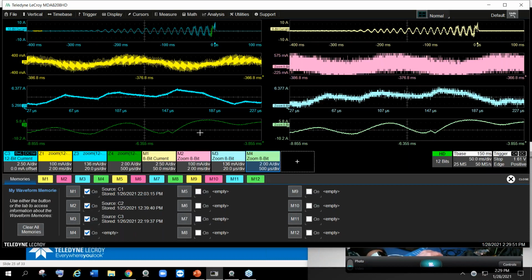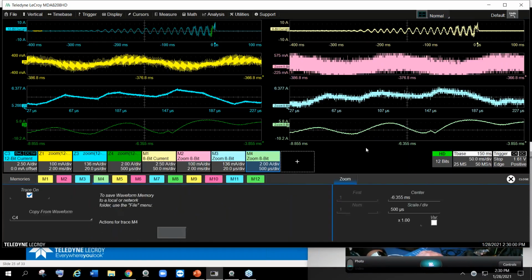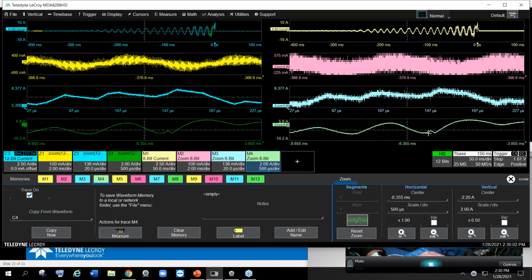So you can see the noise on an 8-bit is significantly higher, significantly higher. This one is a zoom of the 8-bit. Look, that's looking better than I would have thought, frankly. I would flash back this, but nonetheless, you get the point. 256 choices versus 4,000 choices is significant and helps you with your measurements and will also give you the accuracy.